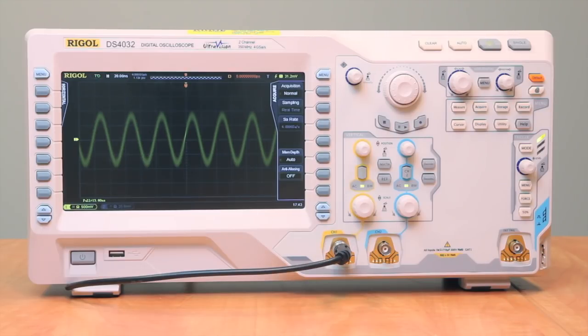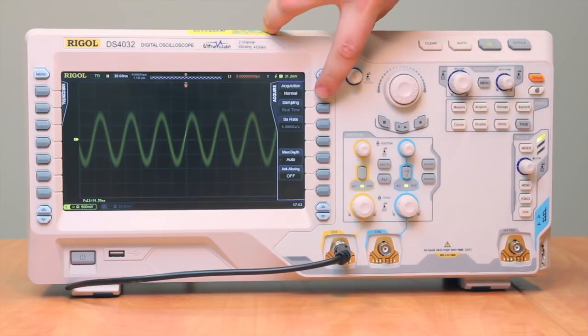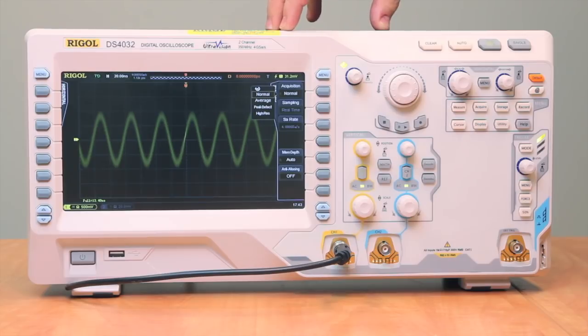And there are really 4 acquisition modes that your scope has that affect how it looks at these, right? So certainly normal is the most common. In essence, normal is picking out a random sample of each sample bucket, right? Because we have 4 gigasamples per second and we're only looking at 10 nanoseconds wide, we still have hundreds of points on this display. So normal picks a close one.